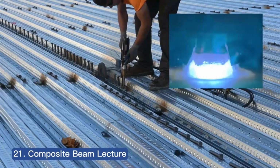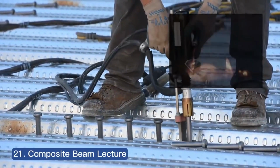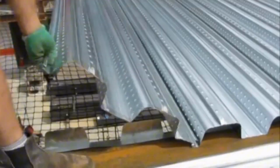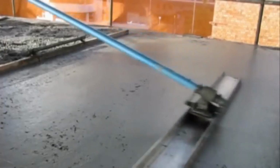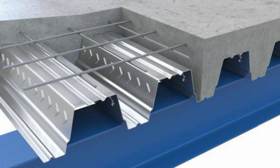One of the main advantages of using metal decking is that it is very fast and easy to construct. Another advantage of using metal decking is that it can lower the thickness of concrete for longer slabs. For example, for a 4-meter span, the depth of the concrete required can be around 130 millimeters, depending on the structural design.